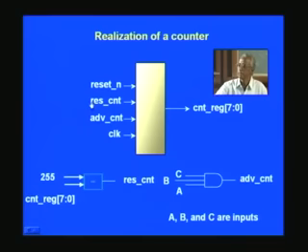And we want to reset this counter when the counter value has gone to a particular value, let us say 255. Then when the counter value is 255, there will be another comparison circuit here, and another signal will be produced here. We call it, let us say, reset counter, and apply it here in this block. And then once you say reset counter, you need to have another signal to start the count. So it is rather an enable of the count. That is what is implied here.